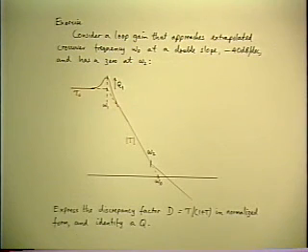And they couldn't figure out what was different, because they hadn't changed anything. Design hadn't changed, specs hadn't changed, the production line was just still the same. Of course, this is the worst kind of problem any company can have, when the customer sends things back and you can't figure out what's wrong. But of course, it requires an immediate crash program to find out. And it took them a long time to discover anything that was different from the way they were doing it before. And finally, they found that the only thing that was different was that they started buying the output capacitor from a different vendor.